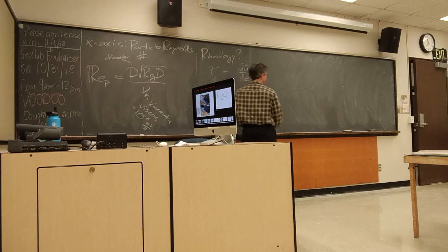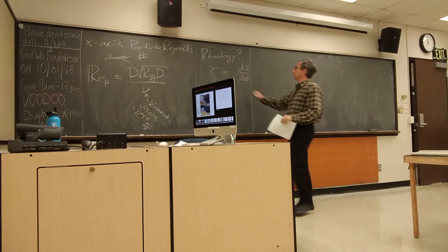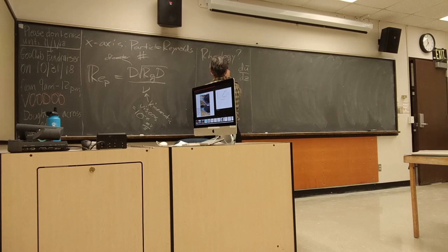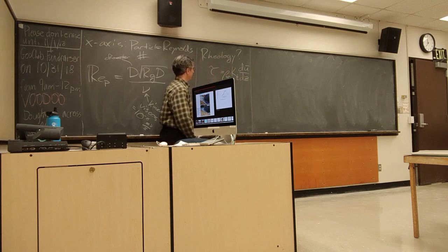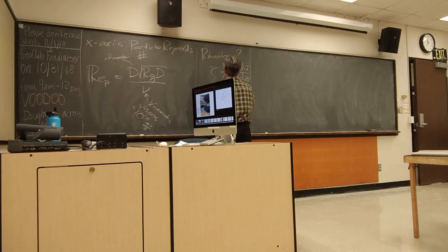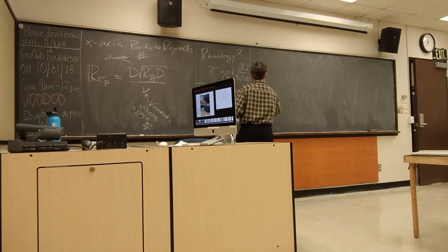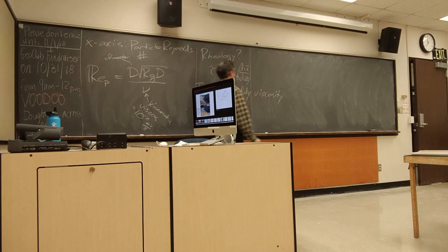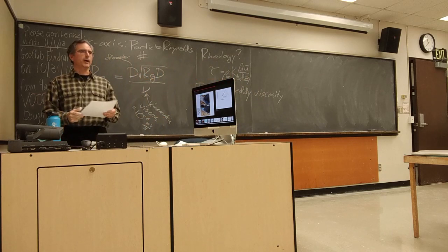And for my proportionality, whereas for regular old viscous flow, I'd put in a viscosity here. I'd have my fluid density, and I'd have my mu or whatever. I'd have a viscosity there, I think mu. In this case, I'm going to throw in a kluge number. And this is called turbulent eddy viscosity. What's up with that then?